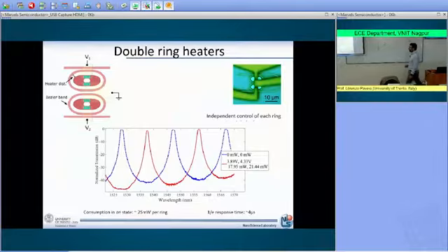And what you see here is that you have a consumption for the microring resonator of only 20 milliwatt, very low consumption, and then the speed at which you can tune the microring resonator is 4 microseconds. Compared to the millisecond in the MEMS approach, you see that we have obtained a very significant improvement.